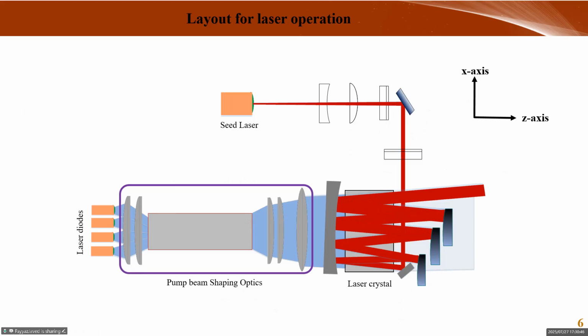But like the thin disk lasers, the non-linearities are very low, while in the fiber laser the non-linearities are very high. But this slab laser comes between both of these technologies. It offers moderate gain per pass and very moderate non-linearities, so that systems can be built with stable output up to 300 to 400 watts of power with picosecond, and a few hundred watts with femtosecond systems.